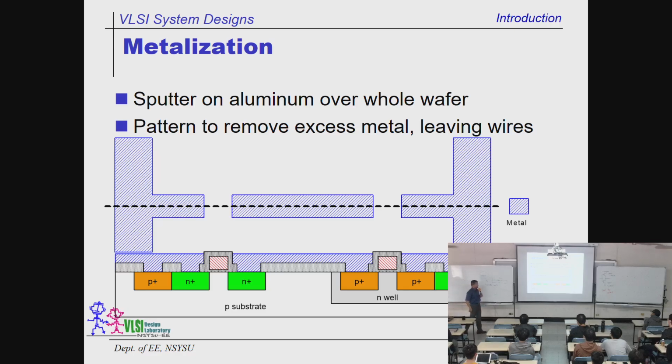And the last one is the metallization. The metal is on the top. So the metal pattern, we do on the machine using... before I forget, all the metal wires that we use are aluminum, not gold, not silver, not copper. I understand the conductivity of silver, gold, or copper is much better than aluminum, but the problem is aluminum is very cheap. It's affordable, so that's why.